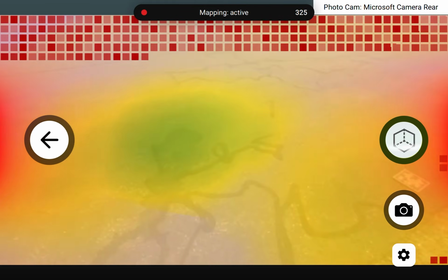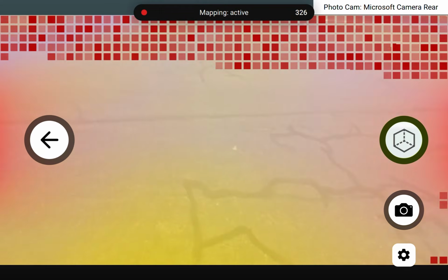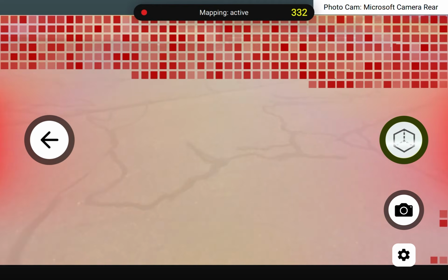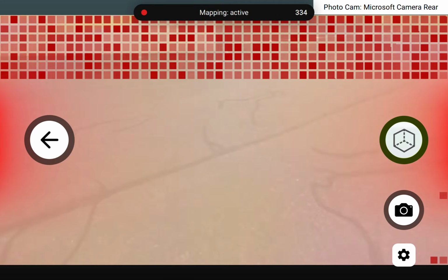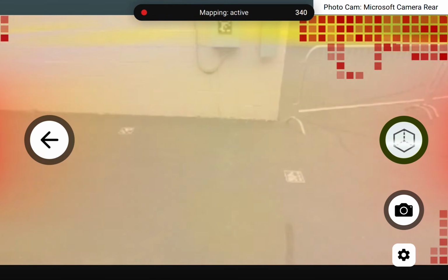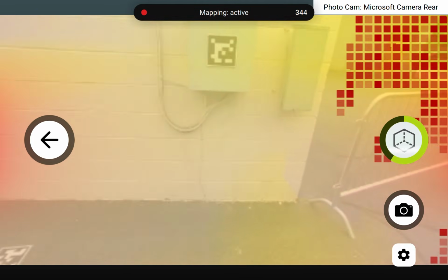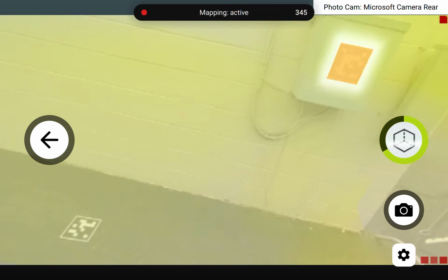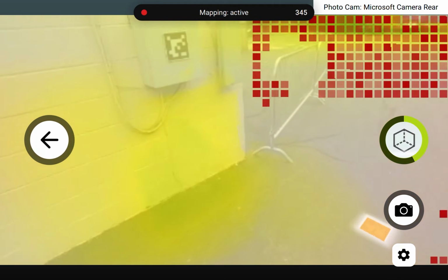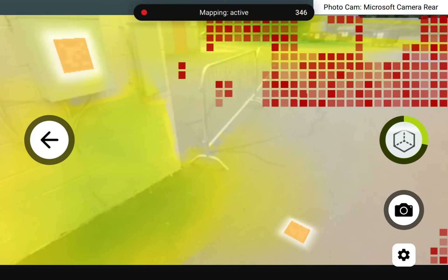And similarly to April tags for loop closure, it's only really helpful when you actually do it multiple times, either on the same or parallel planes. But we're not going to bother in this case. We just wanted to show you how to use it because we are in an outdoor, uneven surfaced environment. So we normally wouldn't actually use that feature in this scenario. We're just pulling it up as an example. It's definitely more intended for indoor, floor wall, staircase type scanning applications versus uneven terrain.